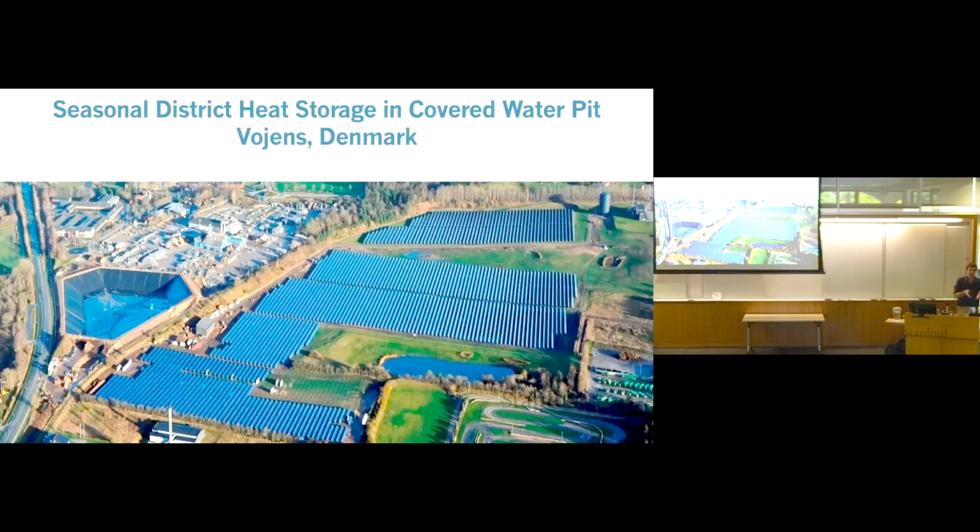That's one thing about the borehole storage. It's nice because you can put it under a field and you can use it for multiple purposes. And the collectors are on the rooftops of garages. So I suppose here you could distribute the collectors on rooftops as well. You can see from this that most of the space is taken up by the collectors, not the actual water, the storage part. But anything with solar is going to take up some area, but the more rooftop we can do, the less land we have to take.